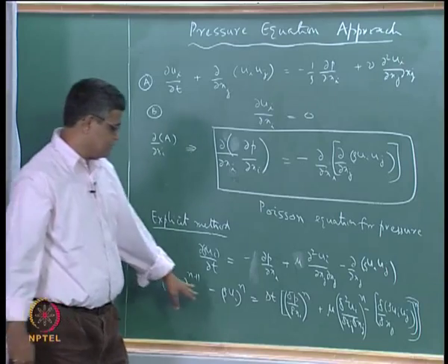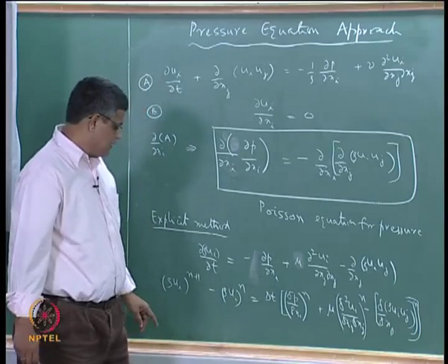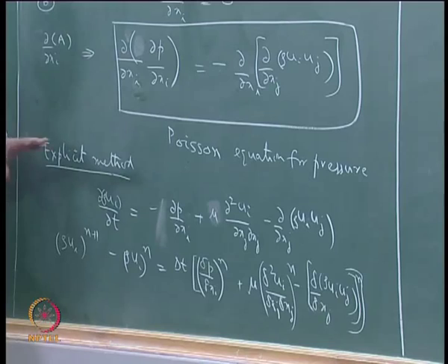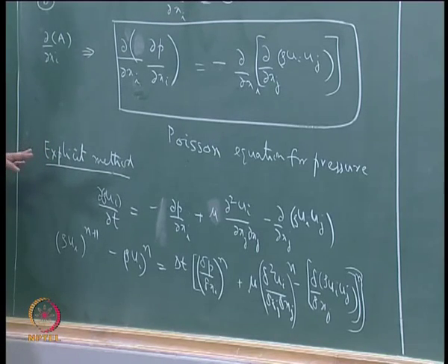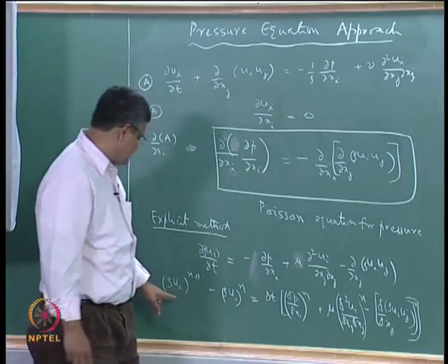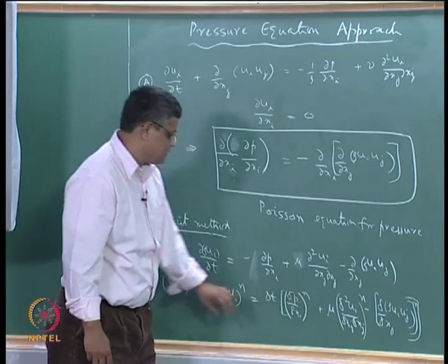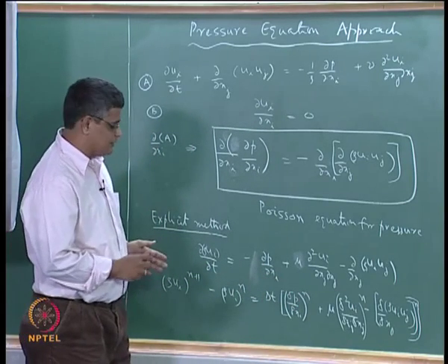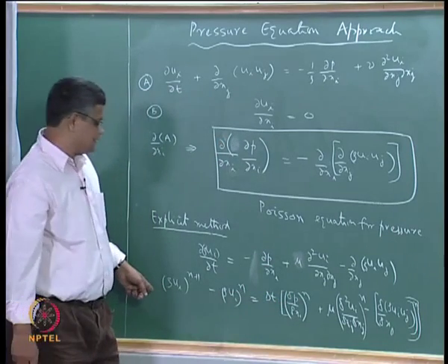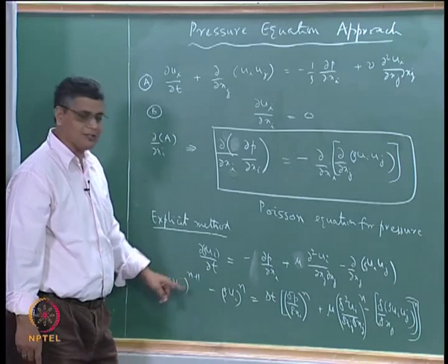Okay. So, this method can be used provided we know this. Now, what we want to do is that, because pressure and velocities are not known readily, we have to make sure that we put the correct pressure gradient in evaluating this. So, we want to make sure that the pressure is evaluated properly at the nth time step, so that using this discretization for the momentum equation will give us the correct value of velocity at n plus 1.